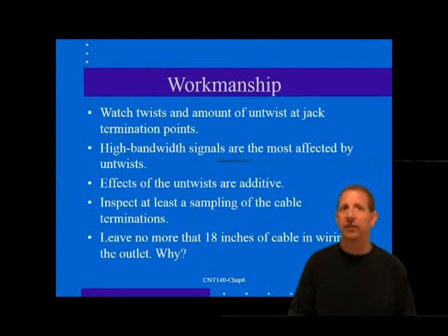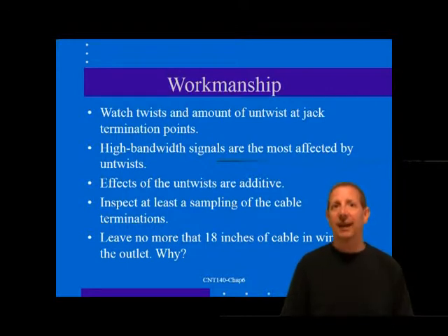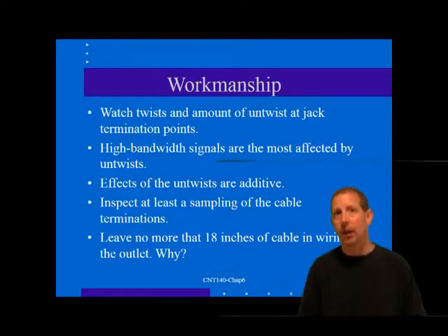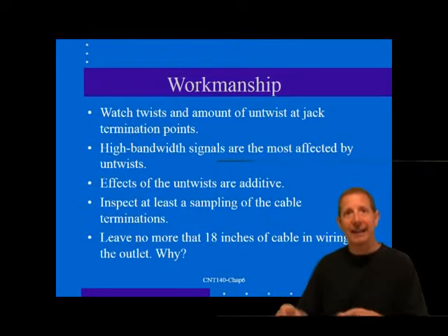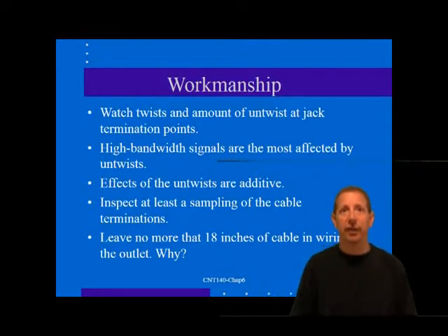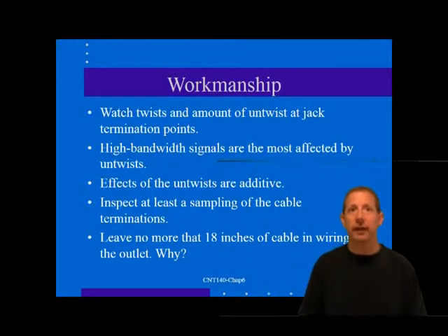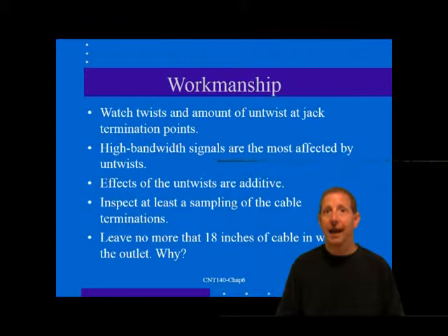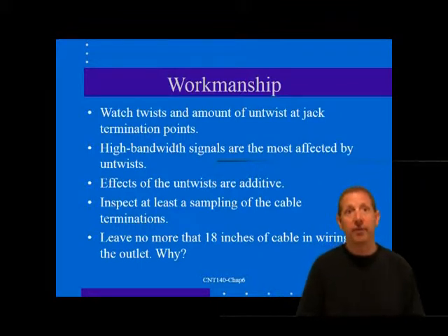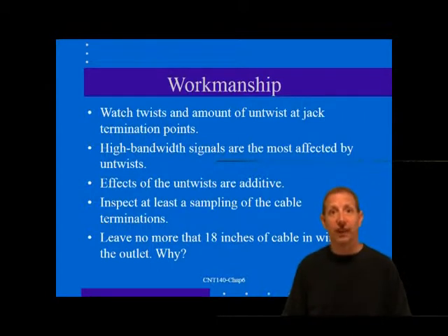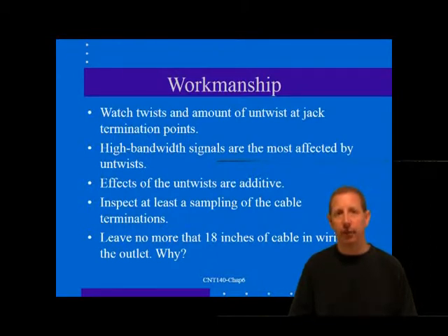Another issue that affects station outlets is the amount of excess cable that is left at the outlet. Standard practice is to leave no more than 18 inches of extra cable length in the outlet. This distance is measured from the wall opening to the jack before it is installed. Excess cable should be trimmed before the outlet is terminated. You should leave a reasonable length of extra cable to simplify the initial termination and any subsequent inspections or re-terminations of a cable run.